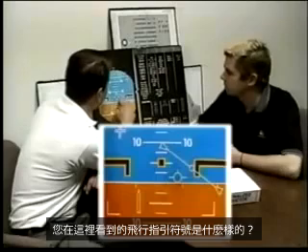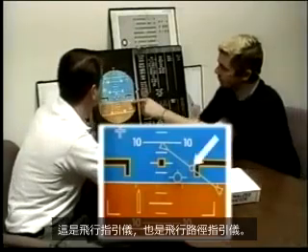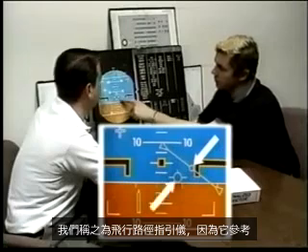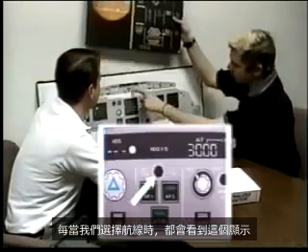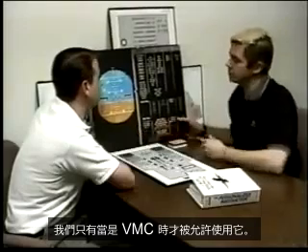What about the flight director symbology you see up here? What do we call that? Okay, this is the flight director, and it's the flight path director. We just call it flight path director because it's referencing the flight path vector. We get this display whenever we select the track flight path angle display. We're only allowed to use this when we're VMC.